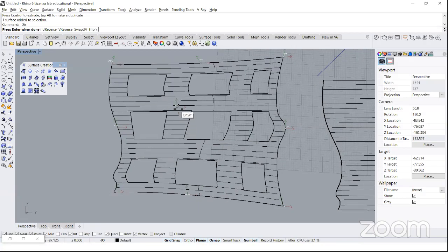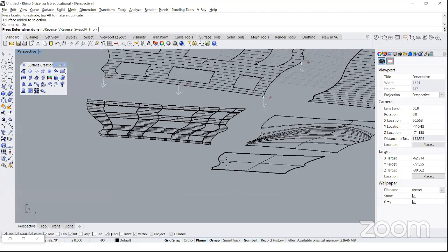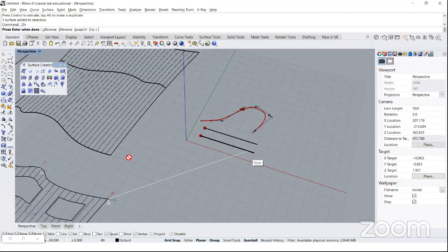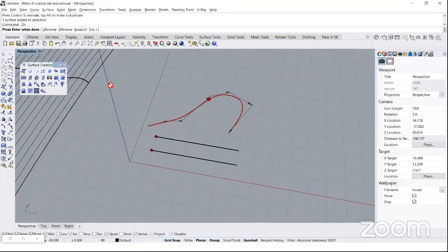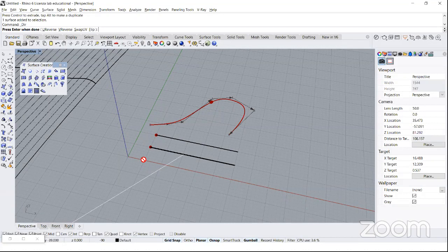I must understand how the U and V axes are oriented. And you see that red is pointing right, which is the U axis, and V, which is green, is pointing up. So here we can recognize the default orientation of any coordinate system: X pointing right, Y pointing up, and the positive Z is the positive vertical direction, okay? So the internal coordinate system of a surface should correspond to this orientation for the three axes.